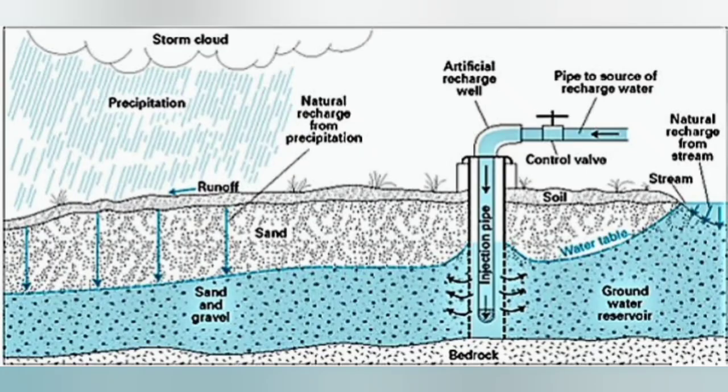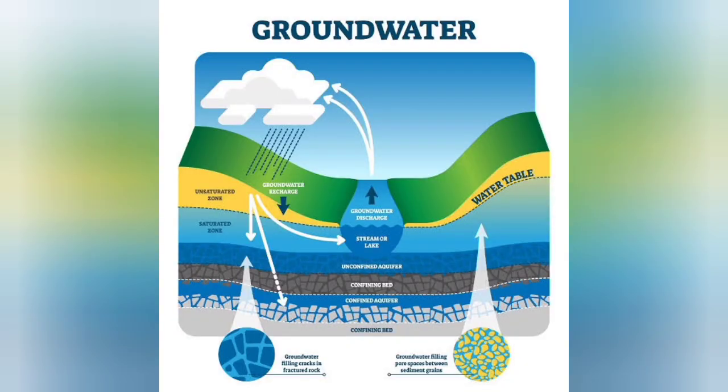And the second parameter in the artificial recharge project is hydrological studies. It is a basic prerequisite to ascertain the availability of source water for the purpose of recharging the groundwater reservoir. For determining the source water availability for artificial recharge, hydrological investigations are required to be carried out in the watershed or sub-basin or basin where the artificial recharge schemes are envisaged.